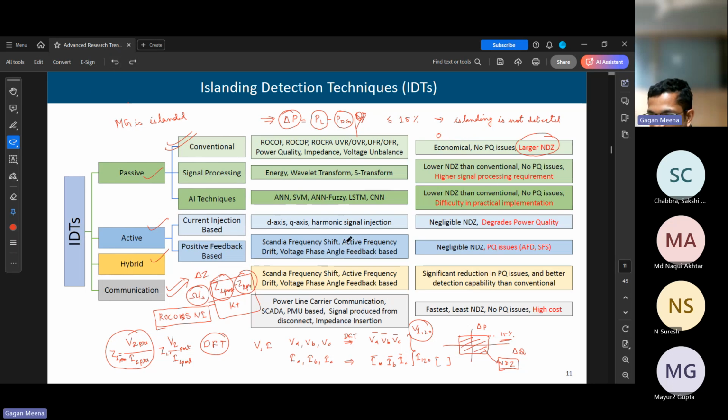That threshold calculation requires a lot of simulation, and it also changes based upon the sampling frequency, because this denominator will change. What is the time difference between the two samples? It depends upon the sampling frequency. So this measure changes with the sampling frequency. That is one disadvantage.